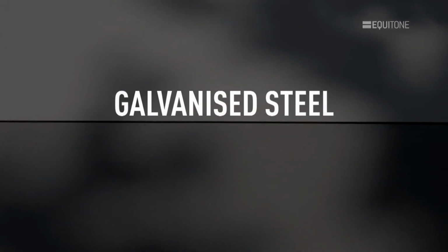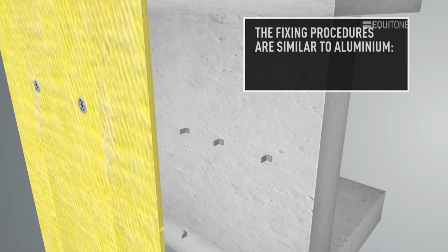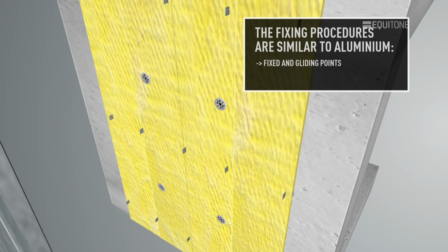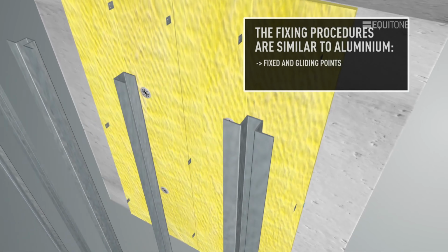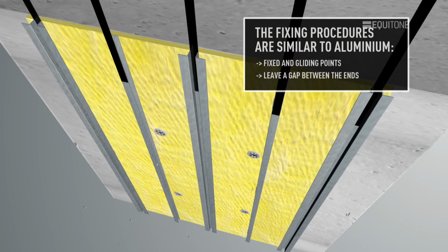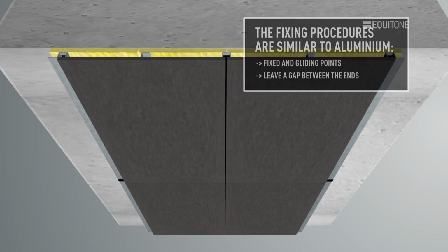Galvanized steel. Although the thermal expansion of galvanized steel is not the same as aluminium, the fixing procedures are similar. The wall brackets are still arranged as fixed and gliding points. Leave a gap between the ends of the vertical omega and U profiles and conceal them by applying the black tape or paint behind the panel joints.